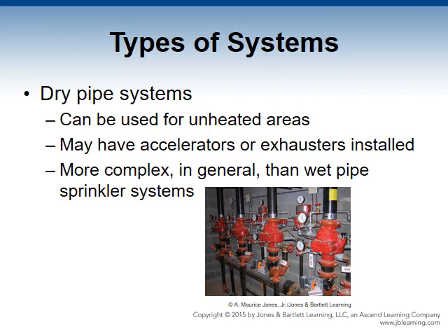Exhausters can be attached to the dry pipe valve or any location where there is a 2-inch piping. They sense rapid loss of air pressure, open a port that purges the air out of the system at a rate roughly equivalent to 15 open sprinkler heads. The process allows the clapper valve to open more rapidly and remove air to accelerate the speed at which water fills the pipes.